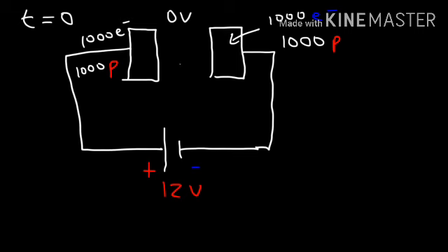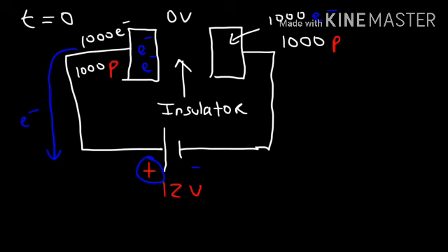Now, mind you, current doesn't flow in between the two metal plates of the capacitor because you have an insulator there. And insulators do not conduct electricity. Conductors conduct electricity. So the electrons will flow from one side to the other side. Now, because this side has a positive charge, the electrons on the left will flow in that direction, and they will continue to flow on the other side. So basically, what the battery does, using its voltage, which you can think of as an electromotive force, it basically pumps electrons from one side of the capacitor to the other side, and that's how it charges it.